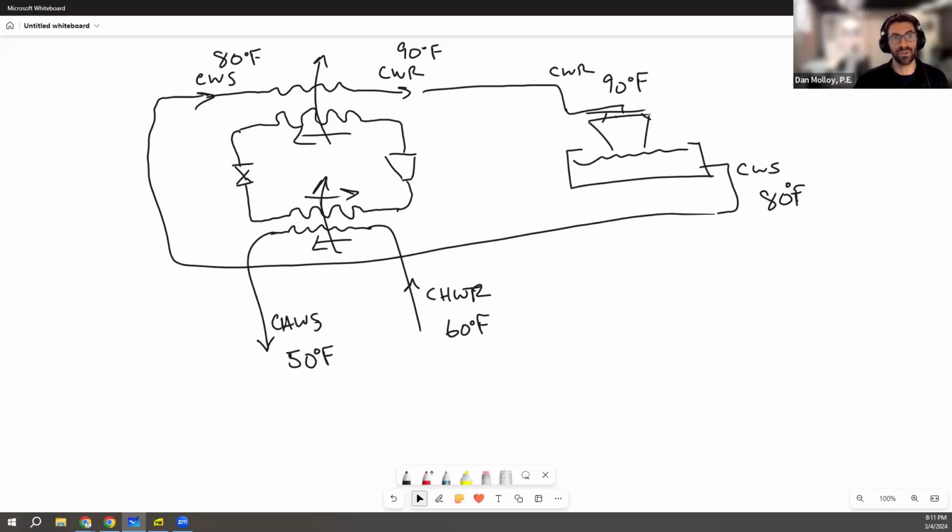that you're not able to use water side economizer, you have to run the chiller. You have to do mechanical cooling. This would be the setup. So what is the hot side? What is the cold side? The condenser water is definitely hotter than the chilled water. That's intuitive. So how could there ever be a situation where we use a plate and frame heat exchanger in place of the chiller and reject heat directly from the chilled water to the condenser water?